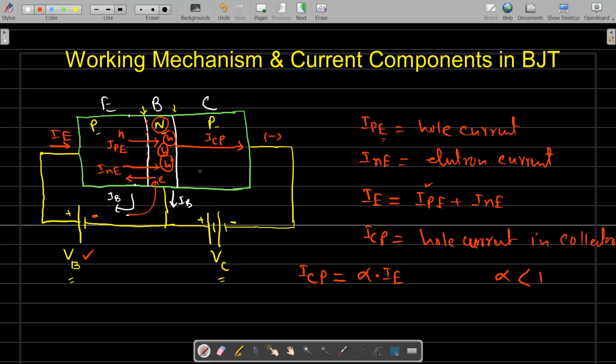That is basically the reverse current, or we can say the leakage current of the device. So let's investigate the transistor. What will be the value of that leakage current? Now see one thing, the base-collector junction is made reverse biased, this one. So we are going to analyze the leakage current component that is between the base and collector region.